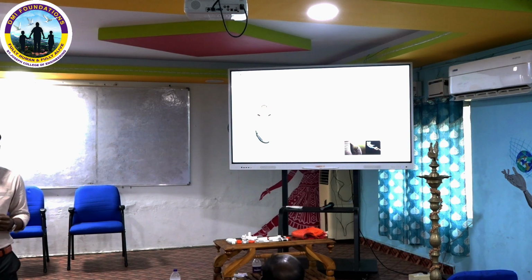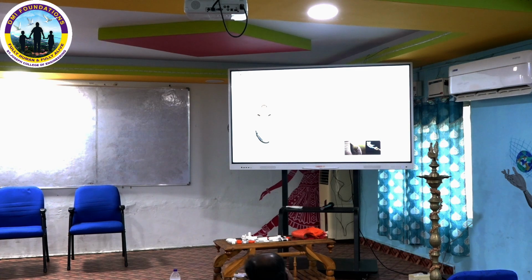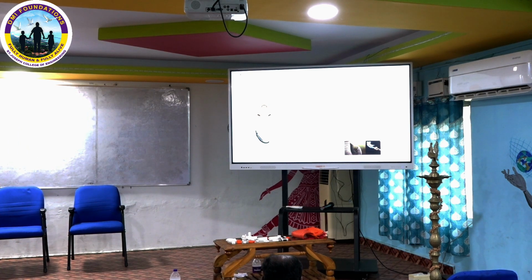Now we need to do CNC coding for that, then we need to select the tool for that. It is hard for the tool to access the particular overhang and other cavity portions to remove the material. But in additive manufacturing, we deposit the material layer by layer only. So we can easily access the particular complex portion and easily fabricate it with the help of additive manufacturing.